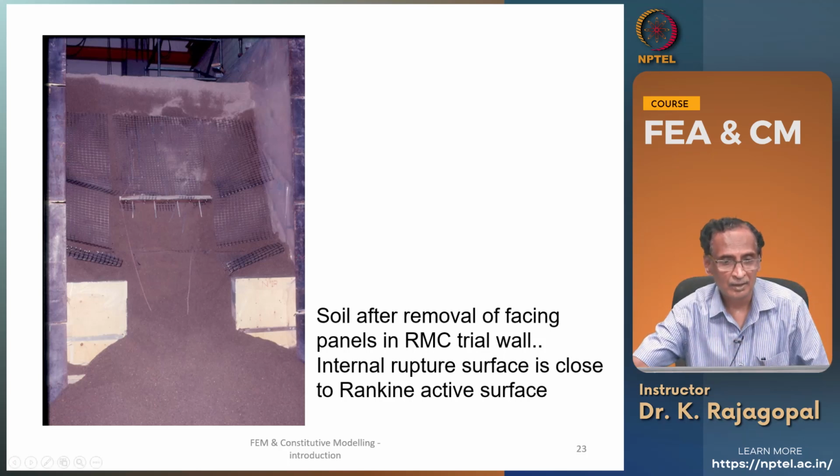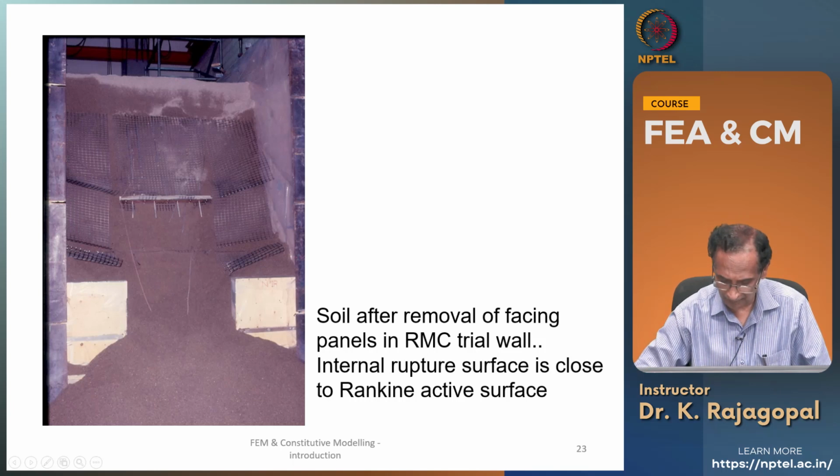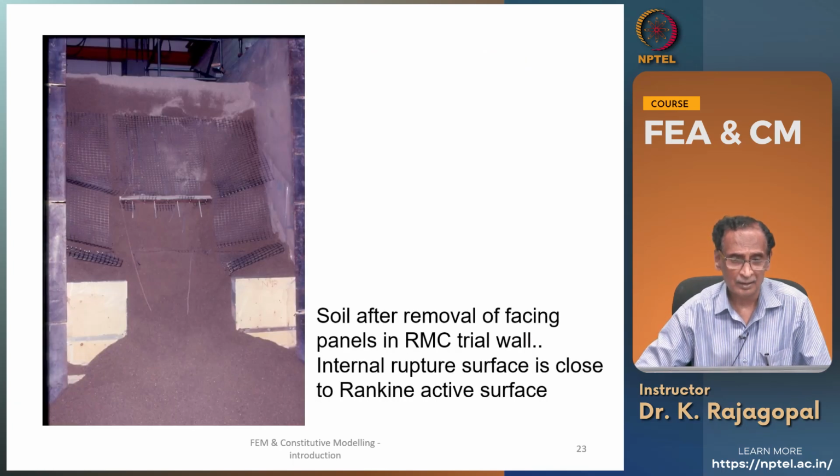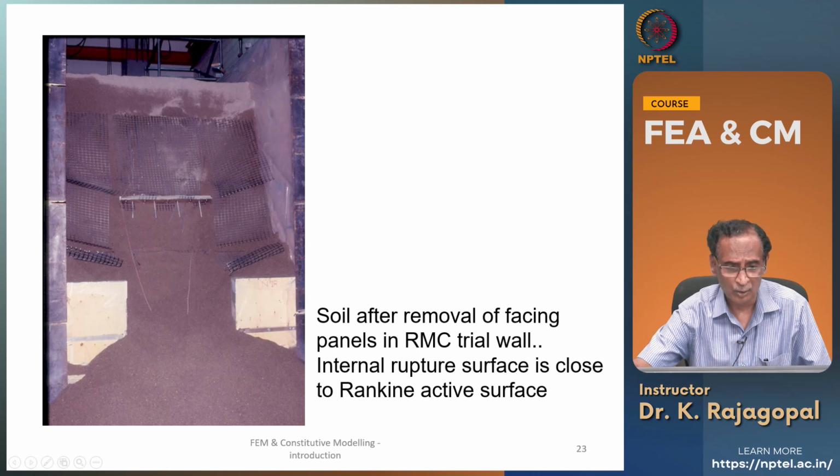And here you see the front panels. You can see some length of reinforcement, and on the front facing there are some panels that were provided during the construction, and after the full construction was over, these panels were removed to look at the internal rupture surface and whether the soil would stand on its own.